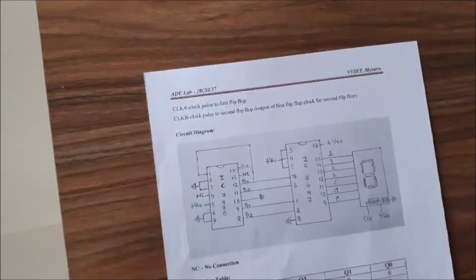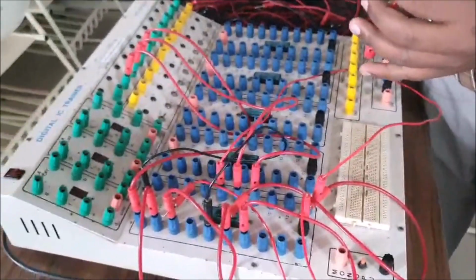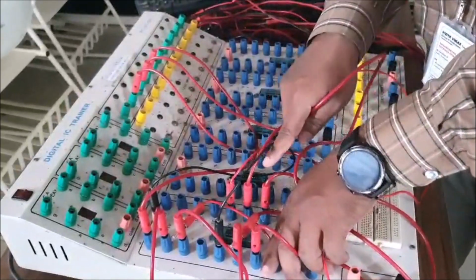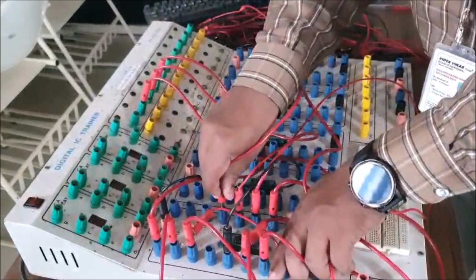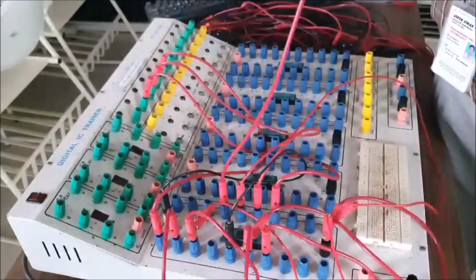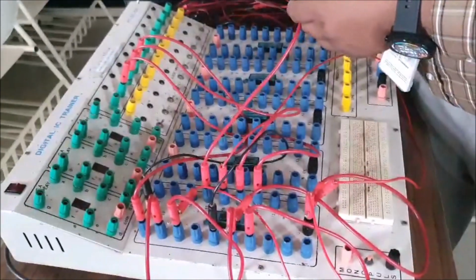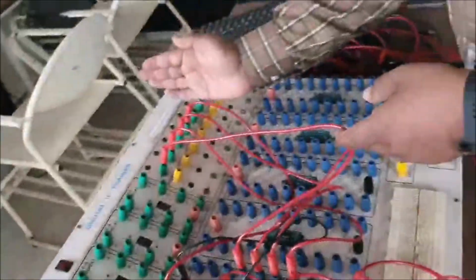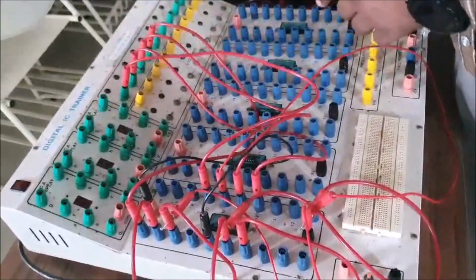Next, moving on to the 11th pin. The 11th pin should be connected to Q3. So I will take one patch cord, and one end is connected to the 11th pin. On the left hand side we have 7, and from the bottom right corner we have 8, 9, 10, then 11. So one end of the patch cord is connected to the 11th pin of 7490, and the other end is connected to Q3. Q3 is the fourth output. So I need to read the outputs from right to left. So this will be the fourth output here.